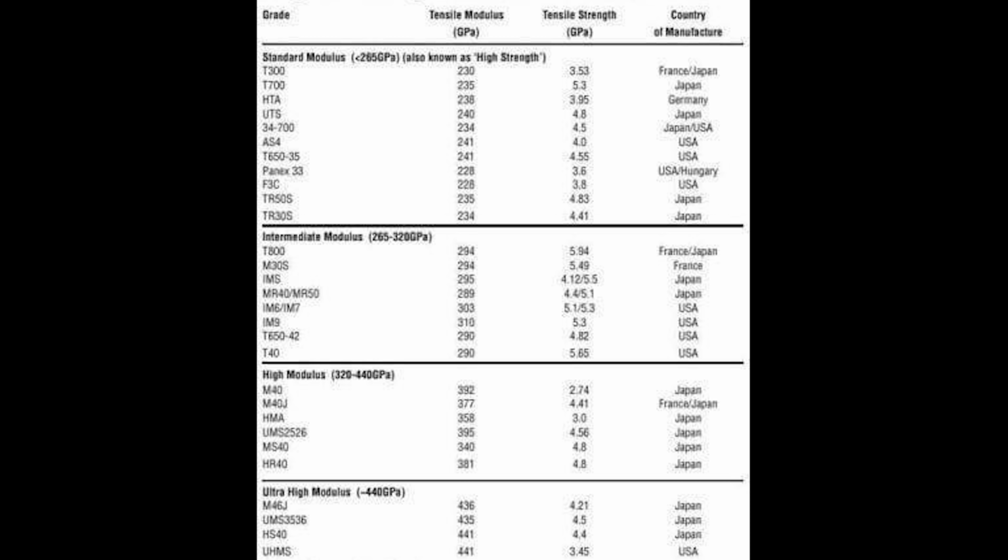Actually, it's very easy to see if a laminate is woven all the way through or not. You can look at the edge. Normally it's really straight layers, which means that it's a UD, and there's nothing bad in that. If it's woven, it's more wavy all the way through. But you don't want that.